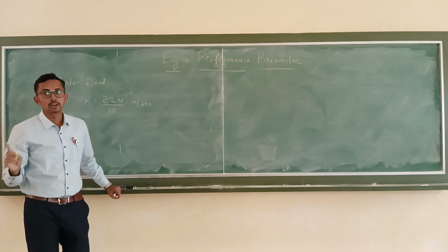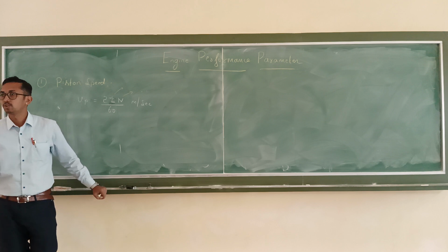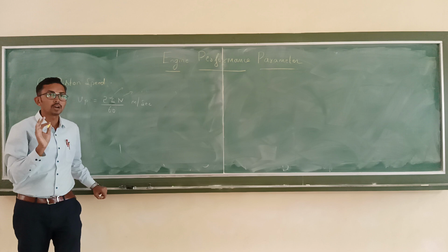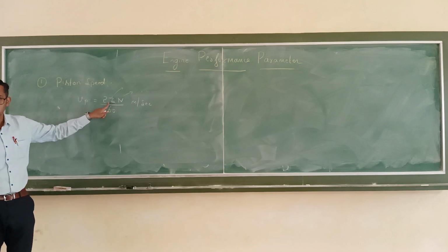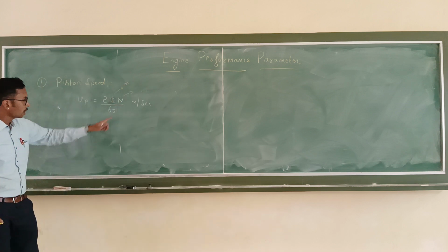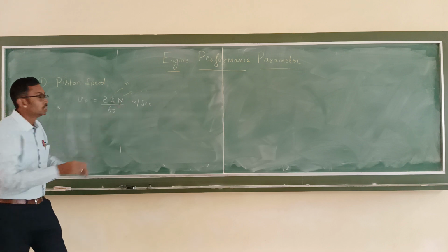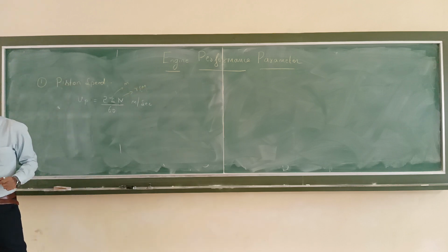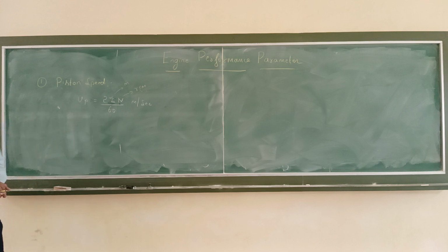If you are not careful about the units, you are going to end up with wrong answers. So be careful about the units. L stands for stroke length, that should be in meters. And N is the engine speed or speed of a shaft, that must be in RPM, rotations per minute. Okay, so this is the first formula.